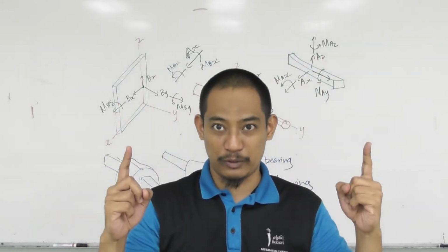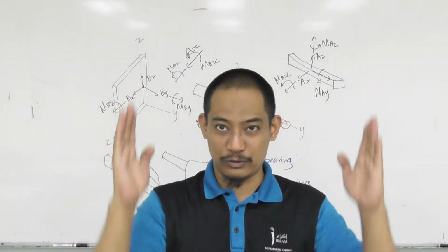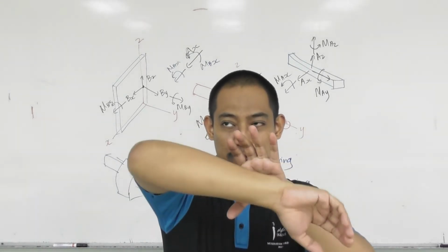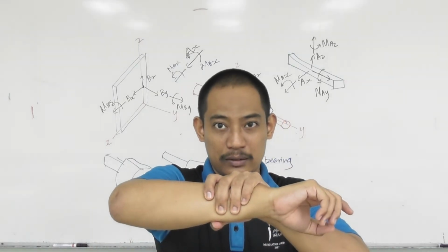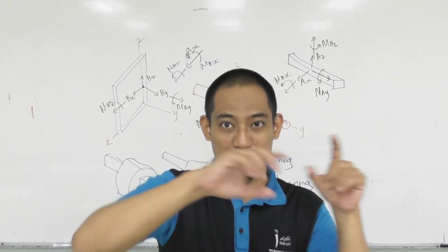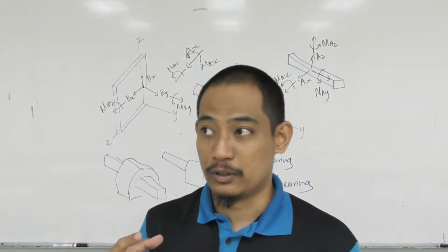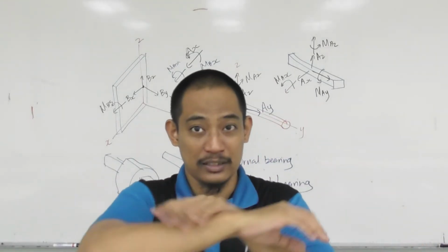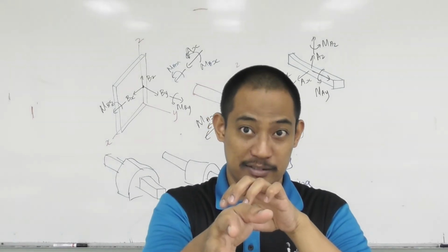So both points will not go up and down. If you imagine that, at the middle it will never have to restrict this rotation. Even though this bearing can restrict this rotation, with these two bearings this bearing will never have to exert that moment. Hence, they say this is properly aligned, so you don't actually draw that Mx, right?